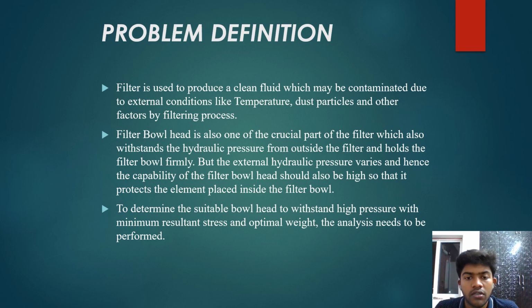The filter bowl head is also one of the crucial parts of the filter, which withstands the hydraulic pressure from outside the filter and holds the filter bowl firmly. But the external hydraulic pressure varies, and hence the capability of the filter bowl head should also be high so that it protects the element placed inside the filter bowl. To determine the suitable bowl head to withstand the high pressure with a minimum resultant stress and optimal weight, the analysis needs to be performed.